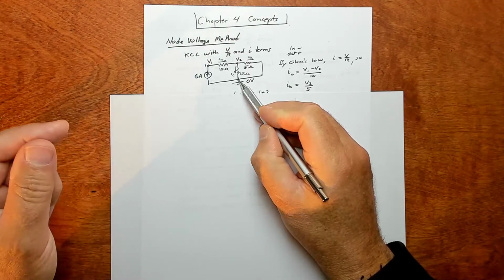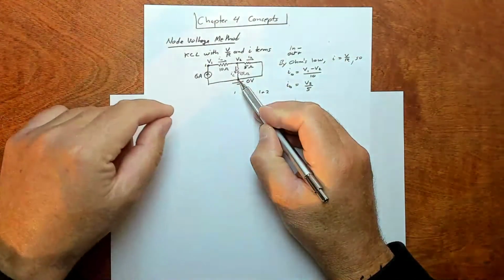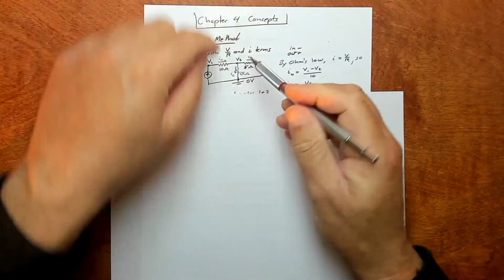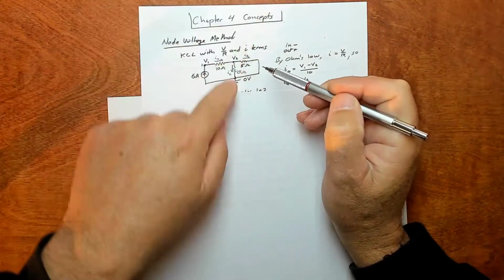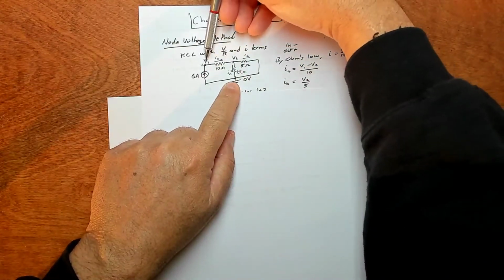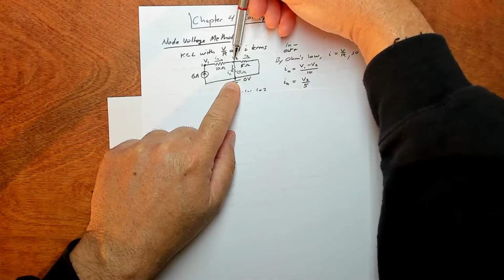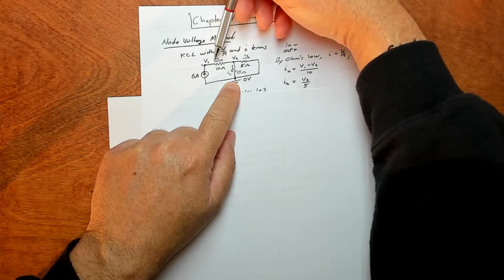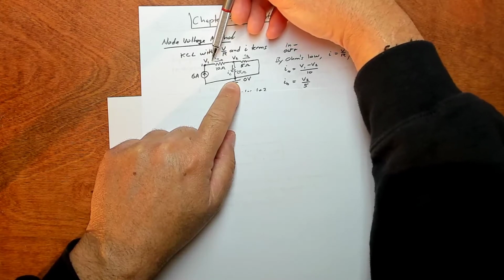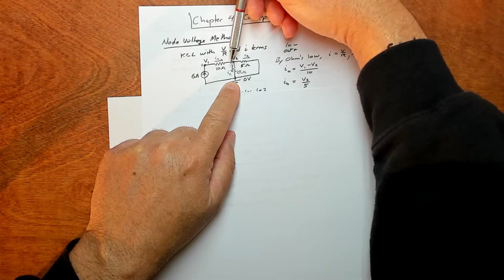But then you take the other wire and you start poking around on the circuit, and you're going to get different voltage readings as you poke around. So if you had the negative terminal down here, and you measured here, you'd get some voltage. And then if you move the wire over here, you'd get another voltage, and it would be less than this voltage. Right? That is, V1 would be bigger. That is, if the current was in fact going this direction, that would be the case.